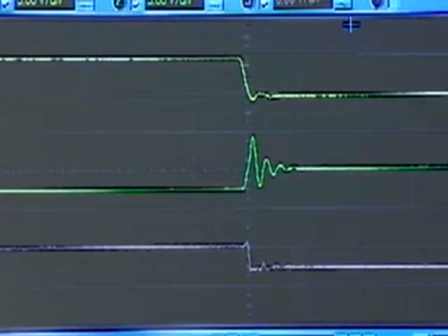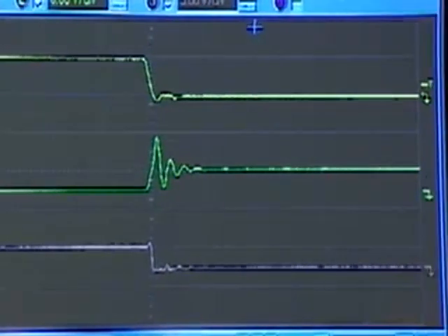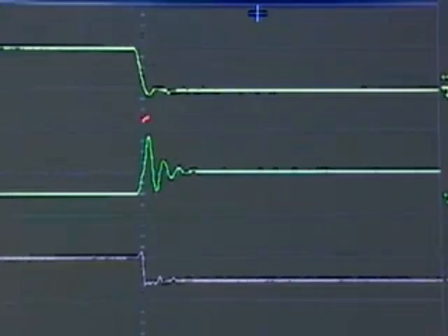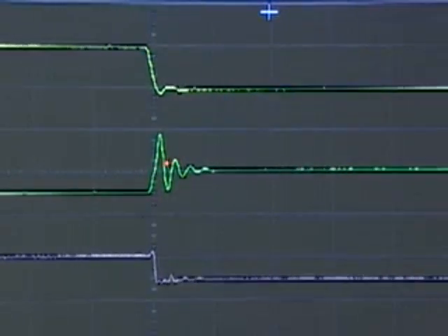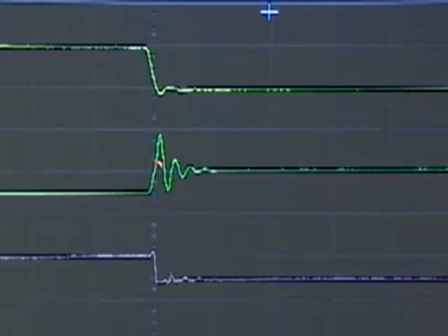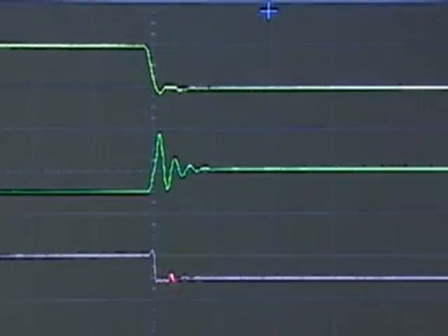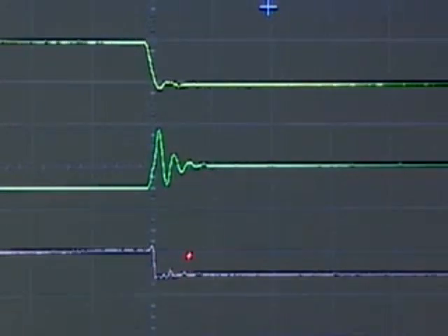Okay, look at this. Look down here. Because this intermediate voltage is meandering all over the countryside here, at this particular point, the intermediate voltage dips quite low. And because it dips quite low, look at the output. The output has a bump here. And it's quite possible for this output bump to now go into the forbidden region. Or worse, if this swing here was higher, this could have actually gone on to a 1. So I would have gotten a false 1 pulse here.